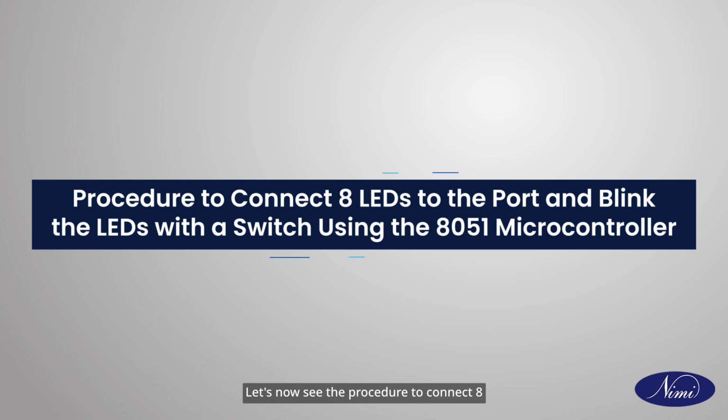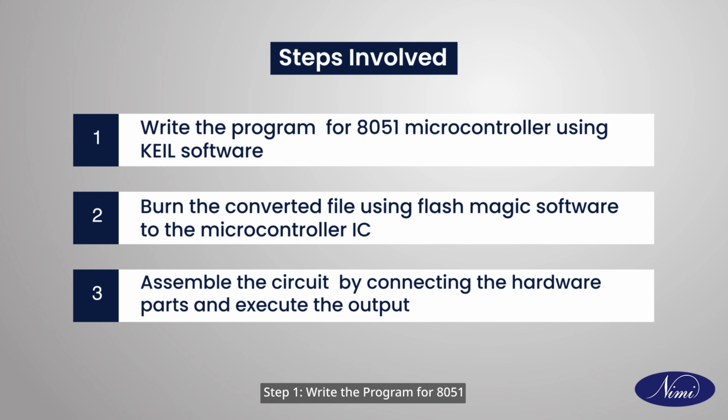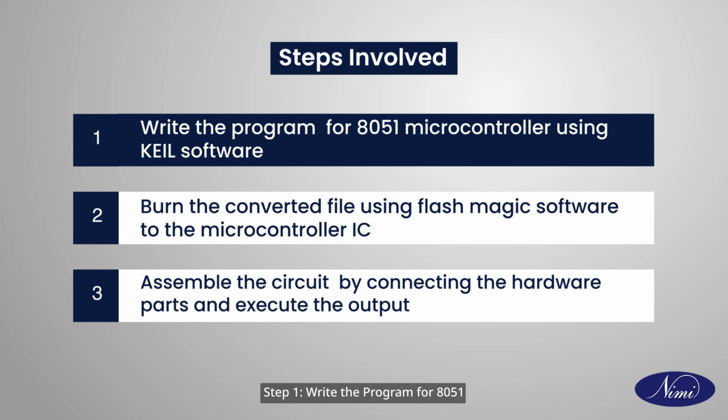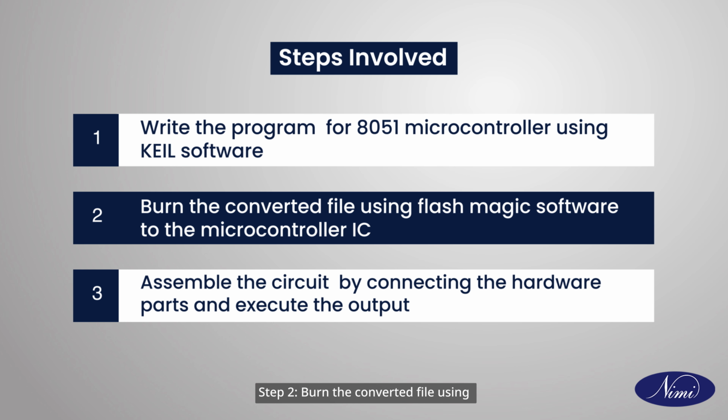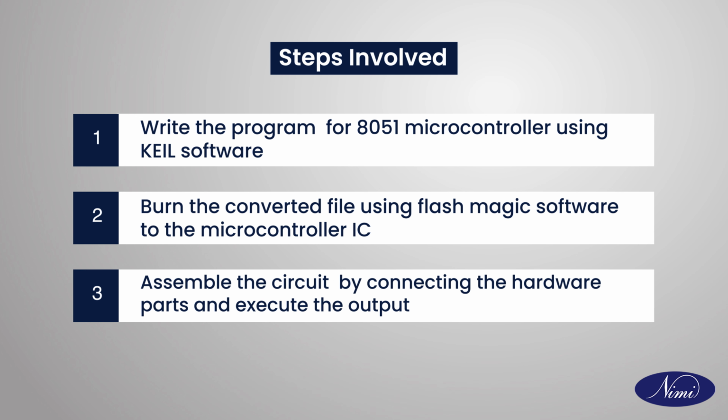Let's now see the procedure to connect 8 LEDs to the port and blink the LEDs with a switch using the 8051 microcontroller. It involves 3 steps. Step 1: Write the program for the 8051 microcontroller using Keil software. Step 2: Burn the converted file using FlashMagic software to the microcontroller IC. Step 3: Assemble the circuit by connecting the hardware parts and execute the output.